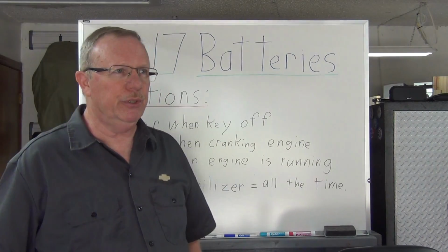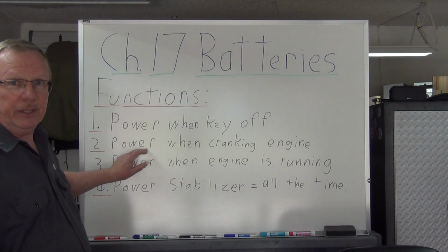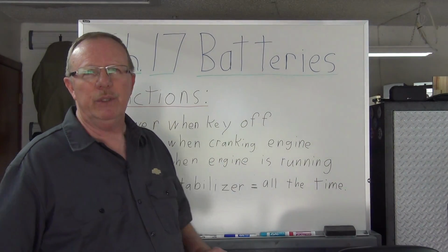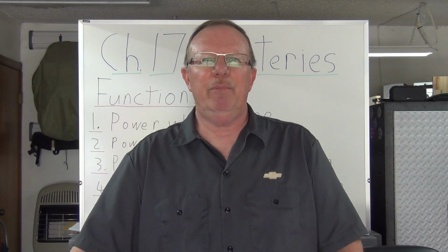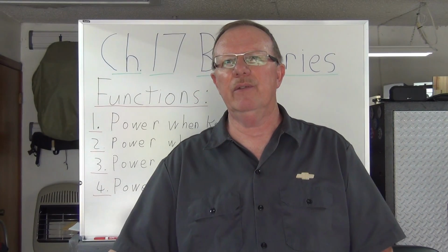Okay? Number two, obviously, we need power, we need voltage and amperage when we're cranking the engine or when we're starting the engine. We have to have power for the fuel pump, obviously. But first of all, we have to have power too for the starter motor, right? The starter motor is one of the highest amp devices on the car, and you know, they run 100 to 150 amps, okay, to turn the engine over. We've looked at that a little bit in class already, if you remember.